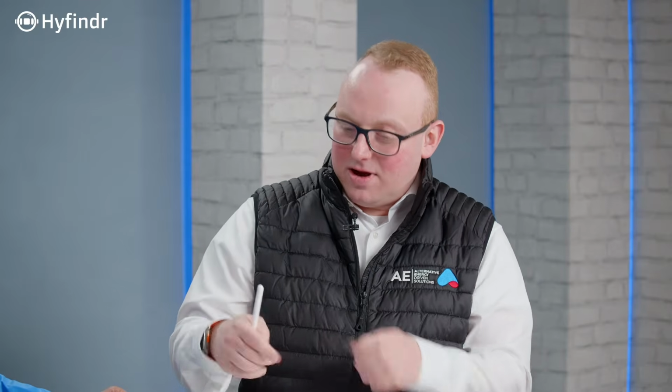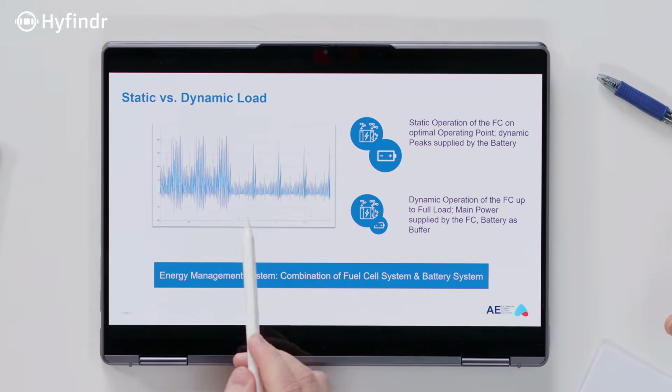So, as mentioned before, you can increase the pressure on both sides, on the anode side and also on the cathode side. But when you increase it on the cathode side, you also need more power for the compressor. And this power is provided by the fuel cell itself. And then there's the question, does it make sense?